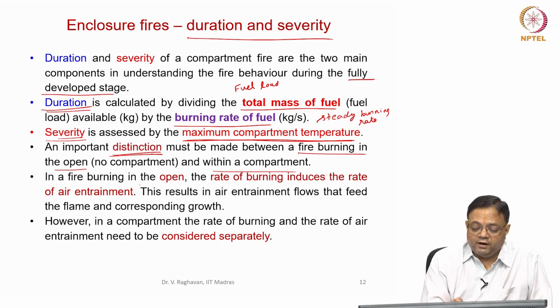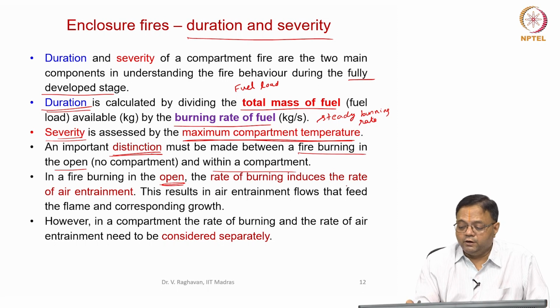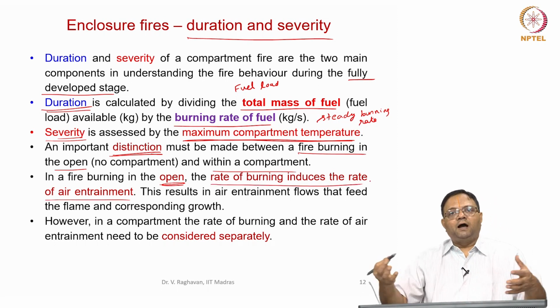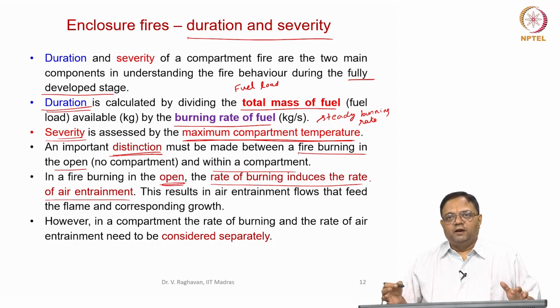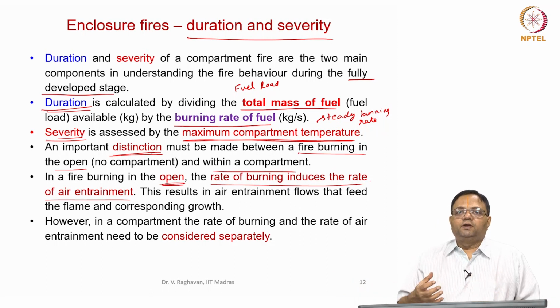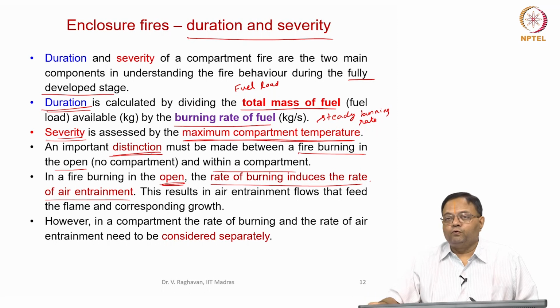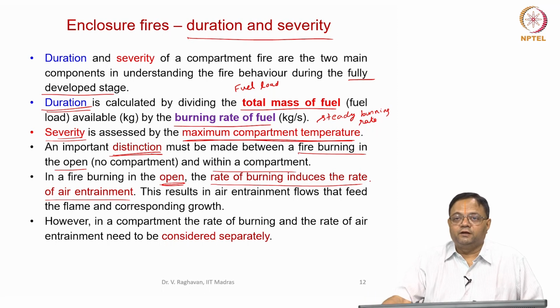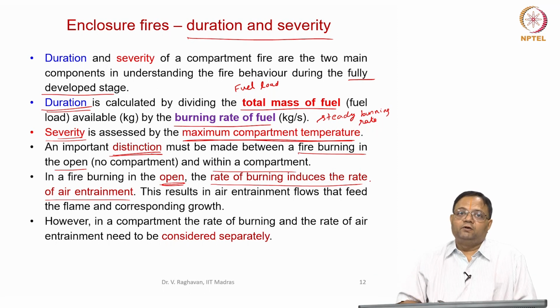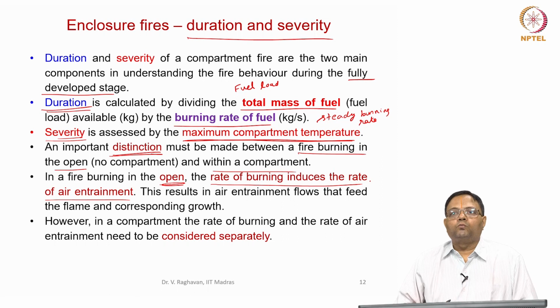Now, when the fire is burning in open, the rate of burning induces the rate of air entrainment, because air is free to entrain. When the rate of burning increases, we will see that the buoyancy force also increases, because the temperature gradient increases, etc. So, due to this, the air entrainment will be increased. The strength of the fire will lead to more and more air entrainment.